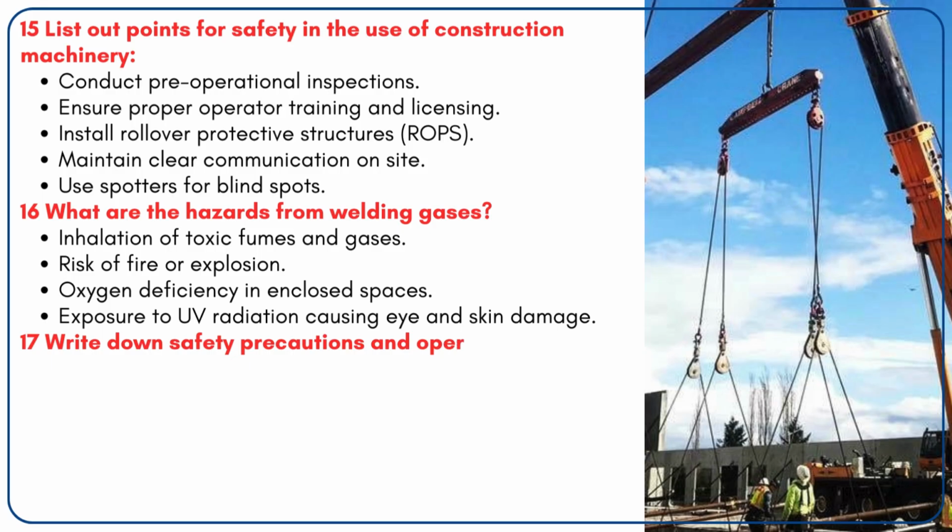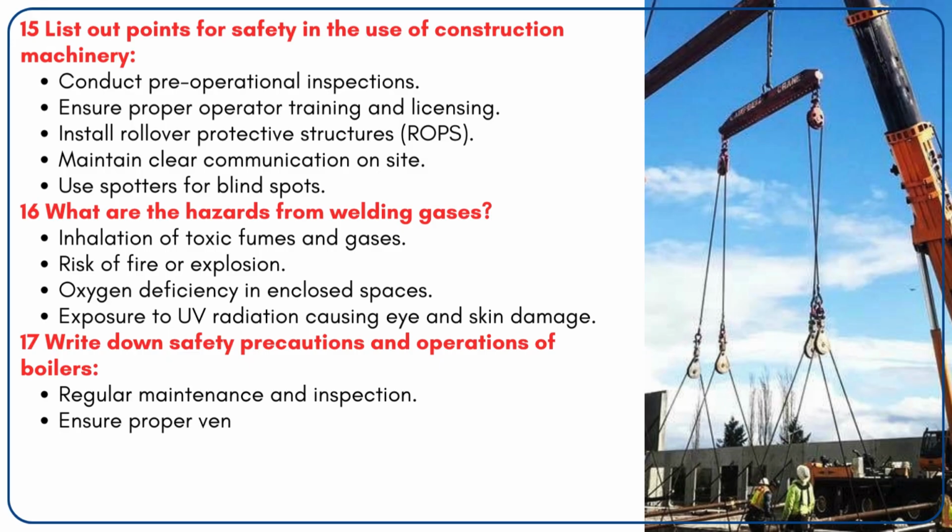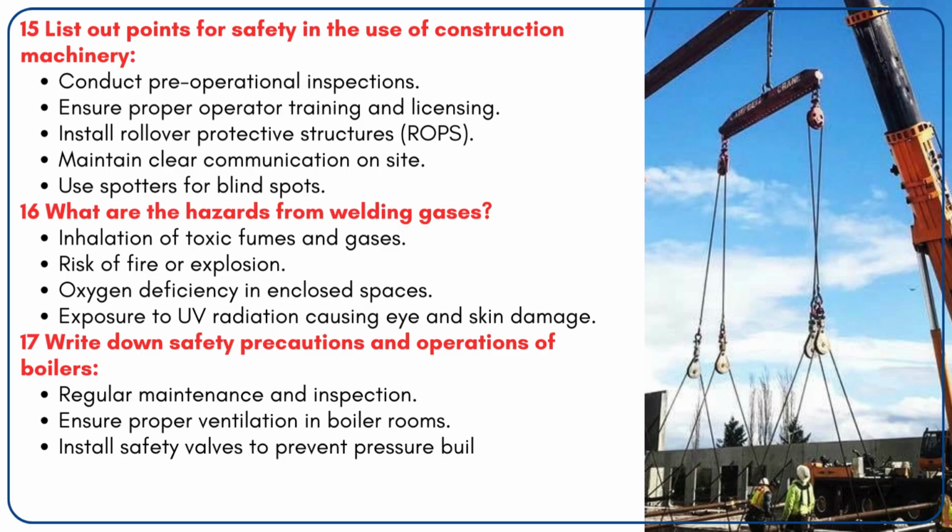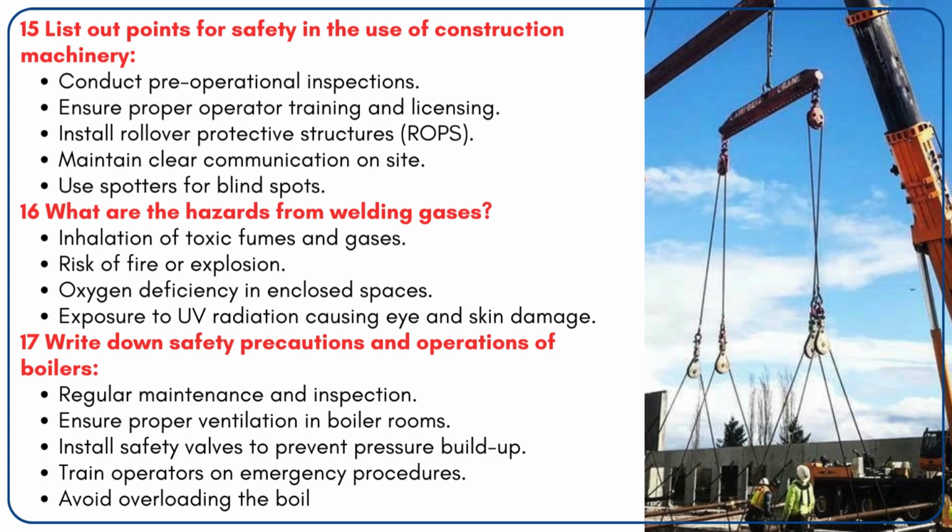17. Write down safety precautions and operations of boilers. Regular maintenance and inspection. Ensure proper ventilation in boiler rooms. Install safety valves to prevent pressure buildup. Train operators on emergency procedures. Avoid overloading the boiler.